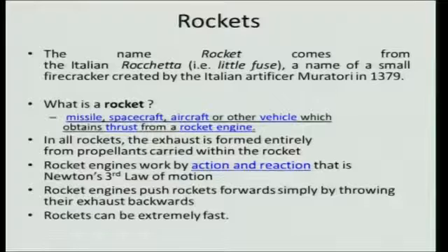In most of the aircraft engines, the main propellant is air, which the engine sucks from the atmosphere, energizes it and then throws it out. Whereas, in the rockets, the propulsion system, apart from the back pressure at the exit of the nozzle, is kind of secluded or independent of the flight, because both the oxidizer as well as the fuel, or all the propellants, are within the rocket. They do not interact with the atmosphere, they do not take anything from the atmosphere, and that is what a rocket engine is.